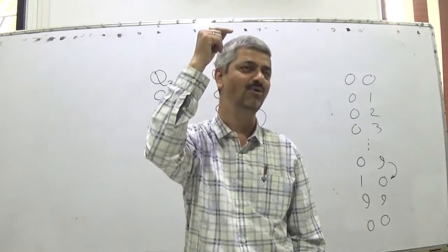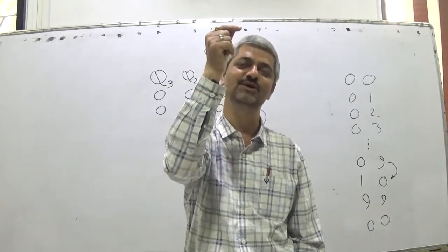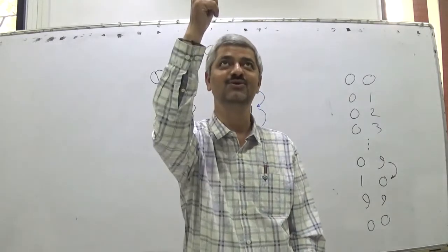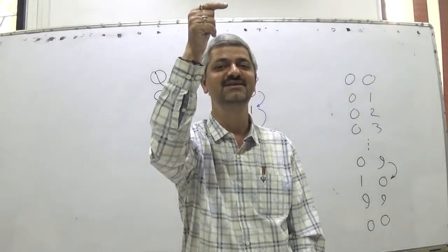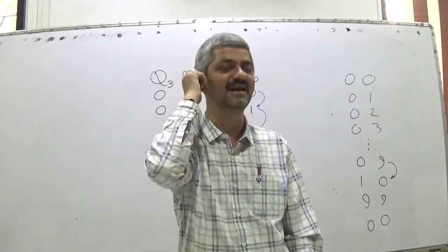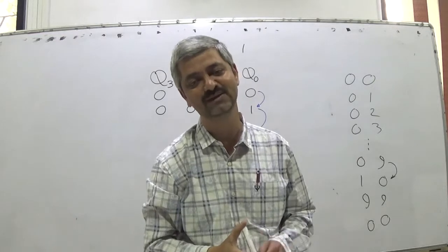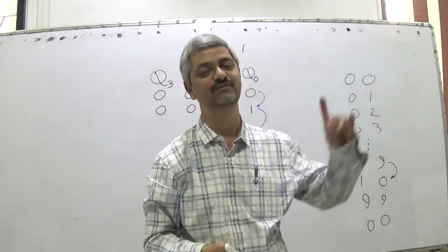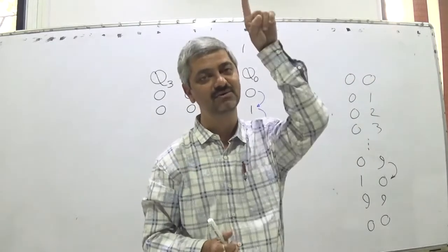If you count up from 0, you move next to 1, and after 1, as it is overflowing, you move to 0. When you are down counting from 0, you come to 1, and from 1, since in down counting you come from 1 to 0, and as you reach 0, again you come to 1. So a 1 bit up counter and a 1 bit down counter are the same in case of binary, whereas in our conventional decimal system, up counting and down counting are different sequences.